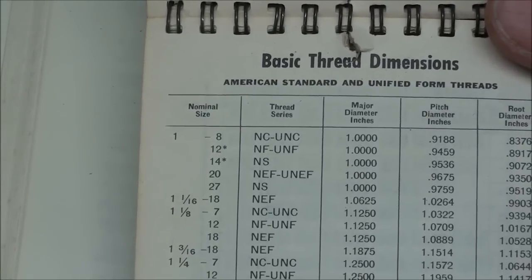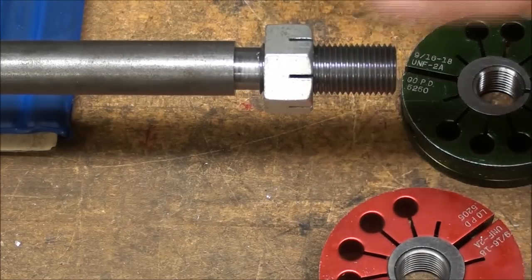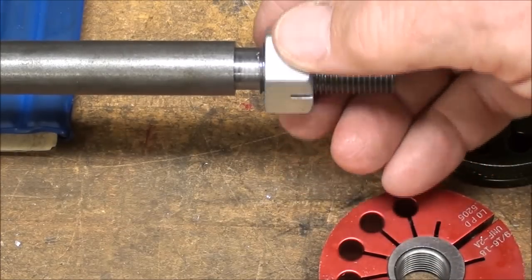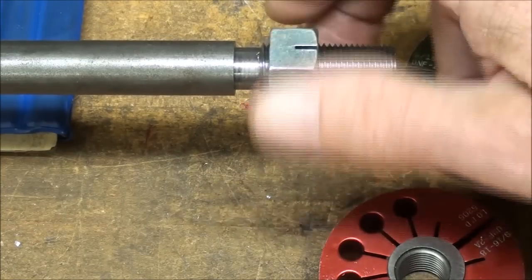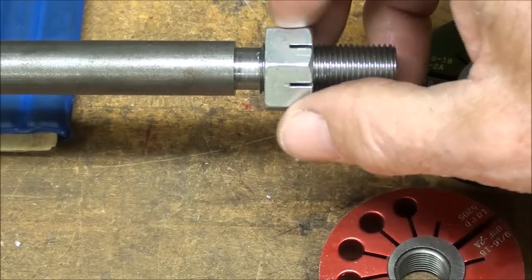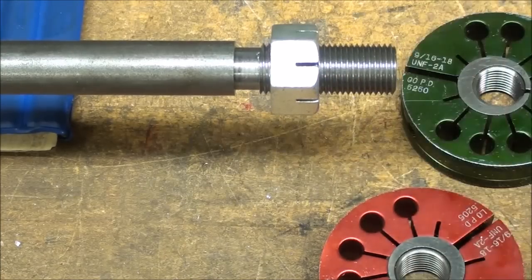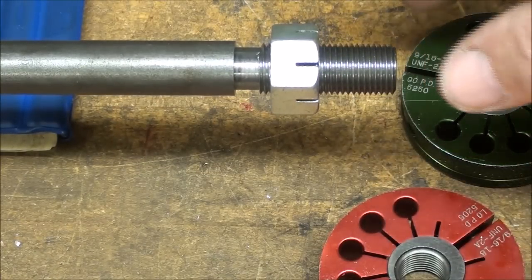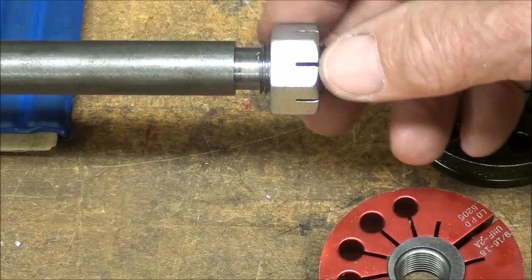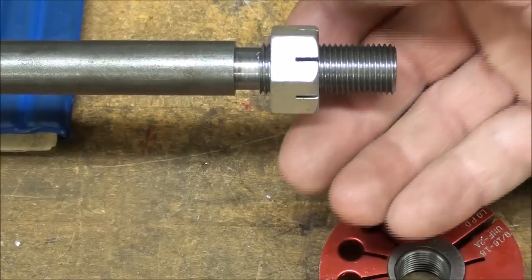Otherwise, let's take a look at how to measure these threads. This is the 9/16 thread that I cut in the last video, and I cut it such that this commercially made nut from a hardware store would fit on easily, and it does. And these nuts, and the bolts for that matter, that you buy at a hardware store are always made to their specification, which are going to be loose enough so they're going to fit when they get them out in the field, and they won't be troublesome and have to be reworked.